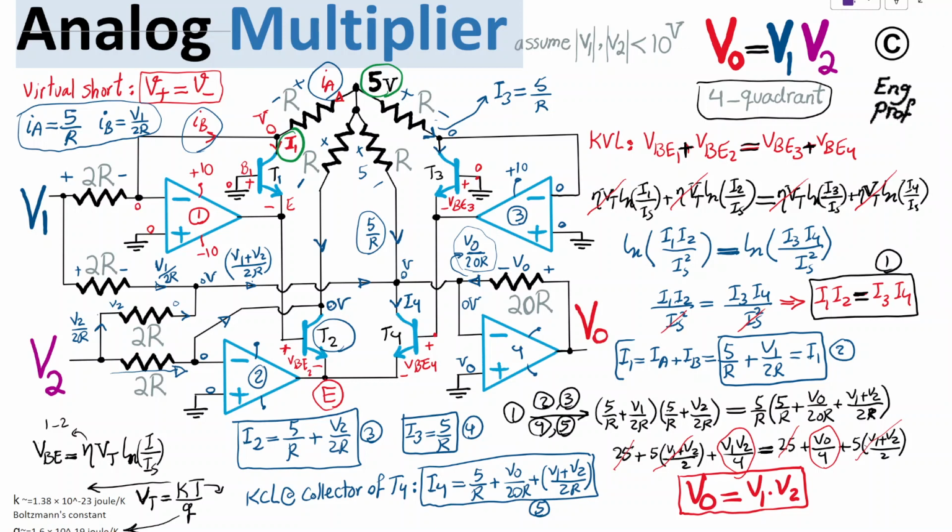In the case that we have negative V1 voltages, that requires a source of current toward V1 basically, so they're sinking current in that scenario. And while the 5/R is providing the needed current for the collector, in that scenario it would also provide the needed current toward V1 when V1 is a negative voltage, of course assuming V1 satisfies the requirement that it should not be more negative than a specific value, otherwise the circuit would not work.